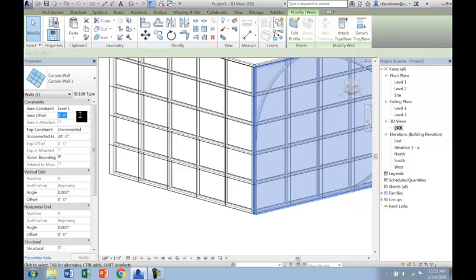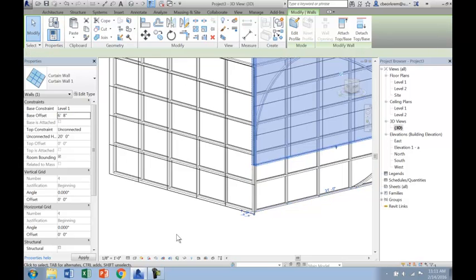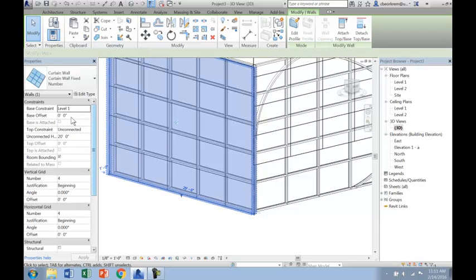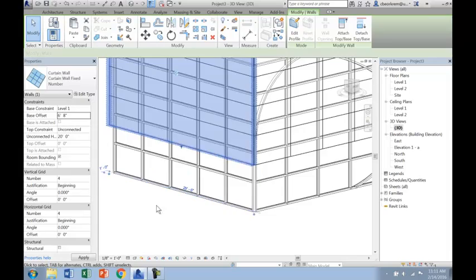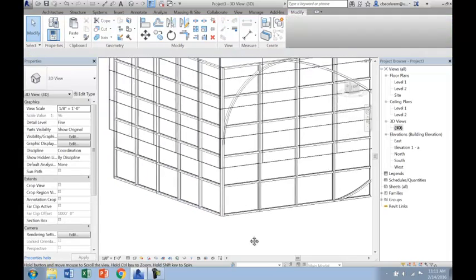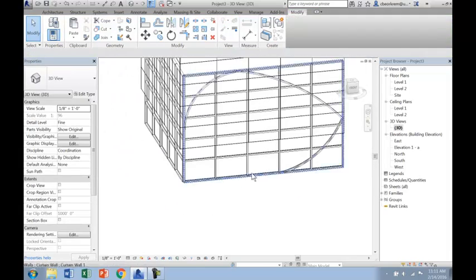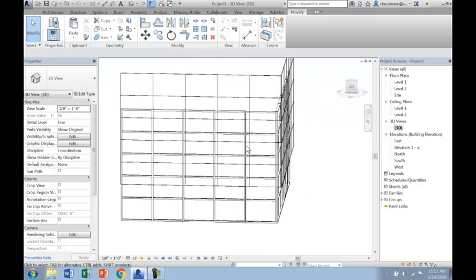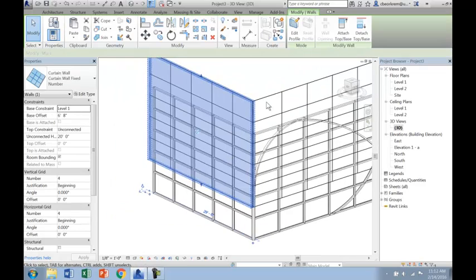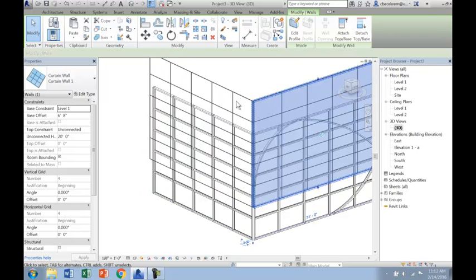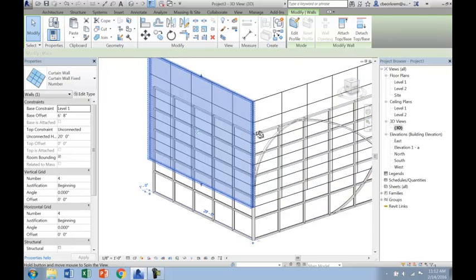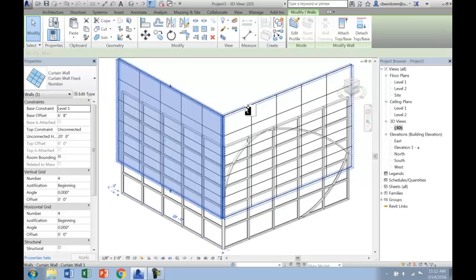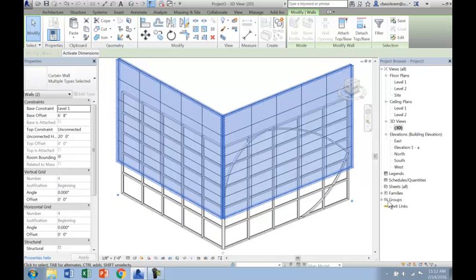So I'm going to offset the base up. Let's do 6 foot 8 inches for both of these, to get those two curtain walls kind of floating up above the doorway where anybody might be working. And you can see I had the unconnected height for both of these set to 20 feet. So we can always adjust all of this stuff by controlling where the levels are at.